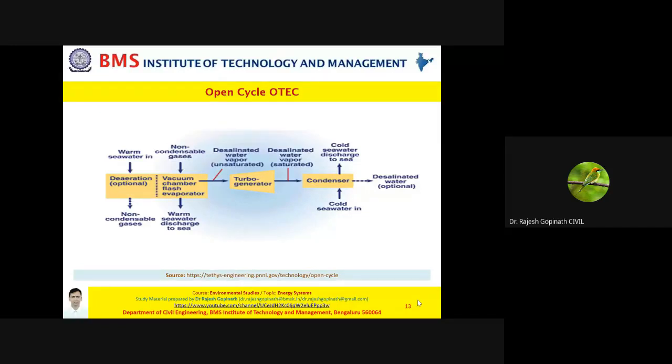Why do I call it open cycle? Because in the condenser, the water vapor gets converted to fresh water, and this fresh water is dumped back into the ocean. So it is open cycle.